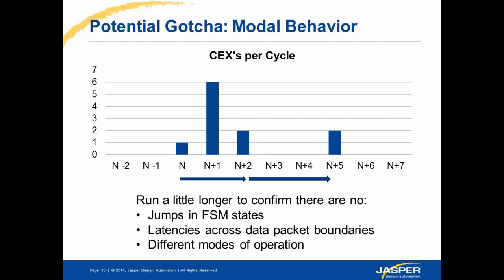So it will come back to you with a number, let's say 30 or 35, and say there is a cover point in your RTL which is being hit at a depth of 35, and let's say you've just run it till 20 or 24. So it says we've found a couple of cover points which are being hit at, let's say, 28 or 32, and you've just run it till 24.